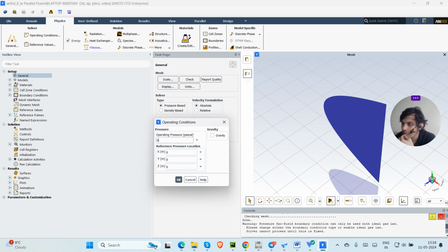Okay. So in Fluent, the absolute pressure is equal to operating pressure plus gauge pressure. Operating pressure is set here and gauge pressure is what the solver calculates. For incompressible flows, the operating pressure is typically set to atmospheric pressure. This allows the solver to compute only the smaller gauge pressures, which helps to prevent round-off errors. For compressible flows, the solver needs to use the absolute values in the calculation. Therefore, it is sometimes convenient to set the operating pressure equal to 0 so that the absolute pressure can be used as boundary conditions.